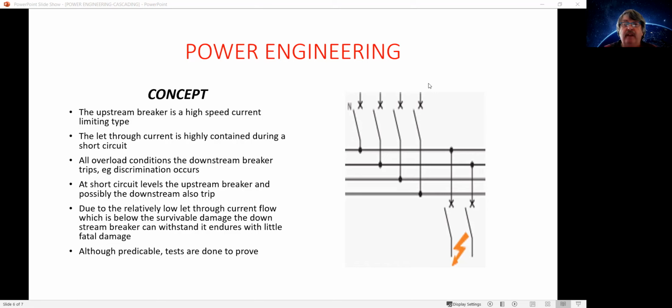It predicts that the short circuit is enough that it needs to be able to trip, and trip finely and fastly and in high capacity, so that the let-through energy is actually reduced. It could very well be that a 50 kA product has, in estimation, somewhere between 15 and possibly 20 kA let-through only. The breaker protects itself by being so fast and efficient, it doesn't actually see the 50 kA. It only really sees something in the region of the 15 or 20 kA. And that's what it's got to survive on.